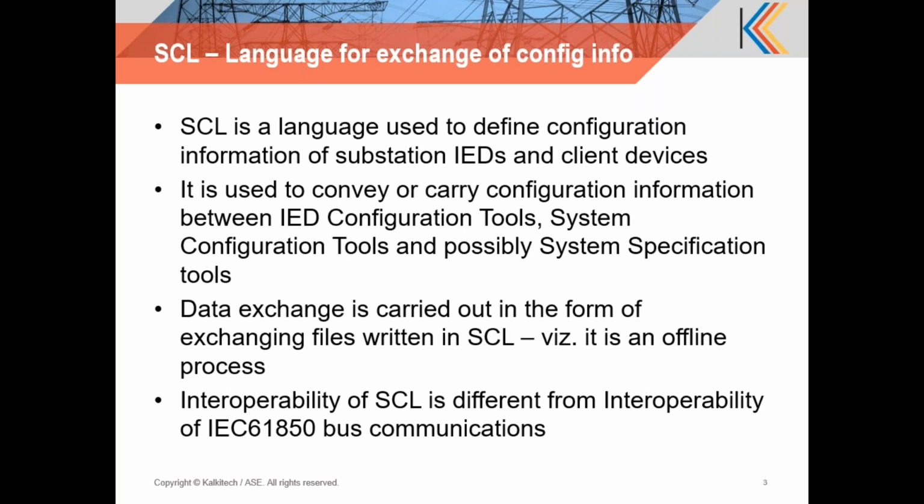There are three kinds of tools that we will discuss. They are the IED configuration tools provided by the IED manufacturers. There are system configuration tools, where you now have the possibility of independent third-party system configuration tools like ours, the one that we use in the demo, as well as vendor-provided SCTs. And finally, the third tool is the system specification tool.